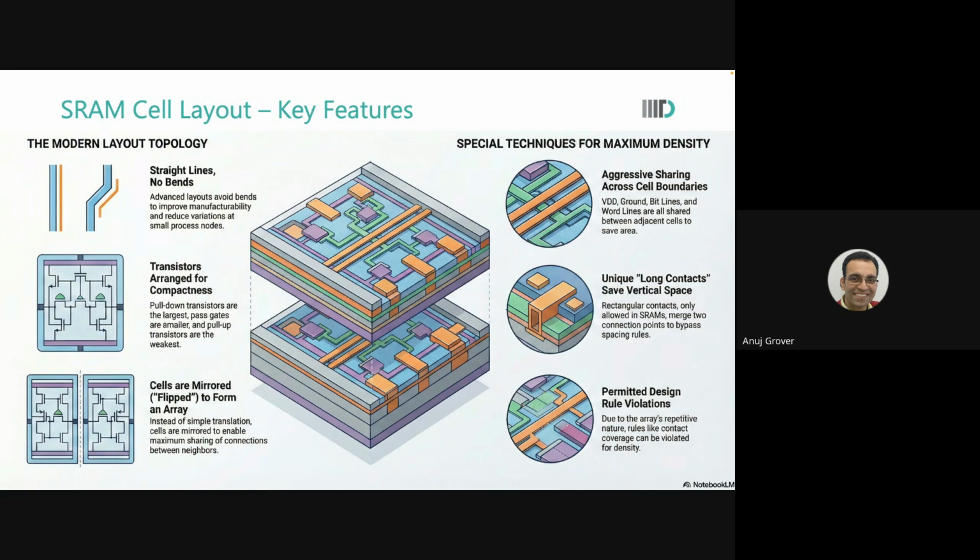Now go open it. And you will see there are additional devices there which are like NPG, HD, something SVT or HVT. That is NMOS, which is used as the pass gate. Then NPD, again HVT or SVT. And then single port has a separate one, dual port has a separate one. You will find that also.